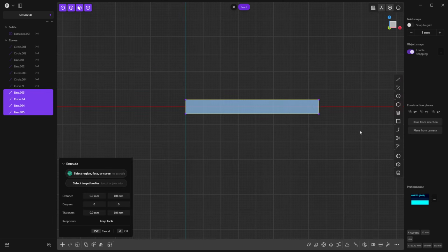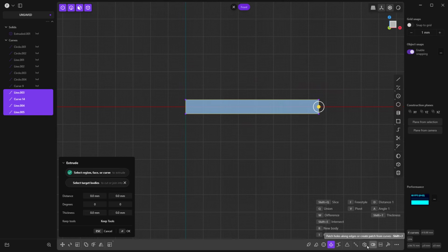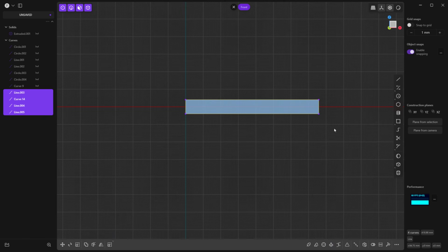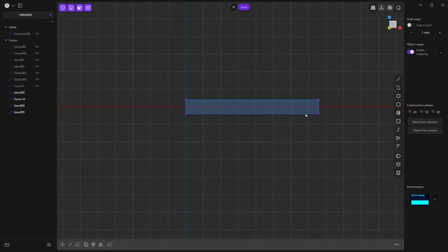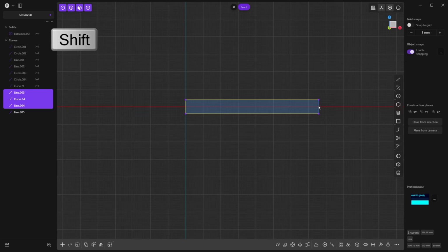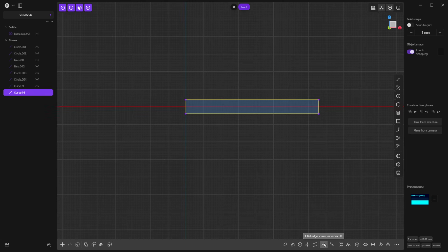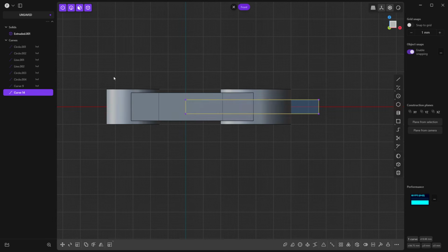These are all 4 individual lines, so I'm going to box select them, and then I'm going to join them together. As we look down here, by default, it's trying to extrude it. I don't want to extrude it. What I want to do is just have the line selected. So I'm going to select each curve, moving our way over, holding down Shift, and notice that now we've got a Join Curves option. Remember, this is contextual, and it's based on your selection. So hitting Join Curves now makes a single curve, and we can easily keep this organized inside of our outliner.